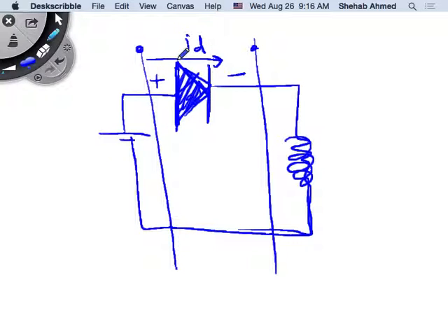So initially, again, an inductor initially is a what? Open circuit or short circuit? Inductor open. Initially, it's just short. So VL is equal to L di/dt, right? So for an inductor, for you to have voltage across it, you need time varying current. So if you supply DC current to an inductor, it will become a short circuit, right? So initially it's an open circuit because it's not behaving as an inductor, it's just a wire.